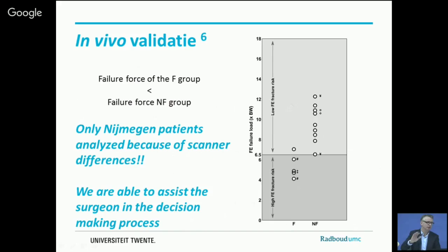Their CT scanners are calibrated almost every day. So the laboratory assistants, they couldn't believe that there was so big a change until there was a big publication in America. They also compared different centers, and it was hugely different. So if you do an analysis as a mechanical engineer and you use CT scans, make sure that you calibrate it. But also, if you do a multi-center study, make sure that that calibration is done everywhere to the highest standard.